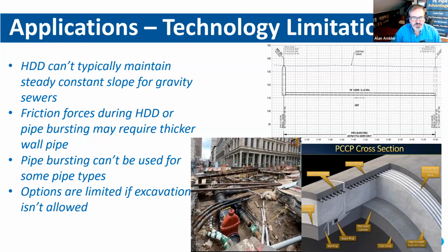So we just had a question from Randy about what types are suitable for pipe bursting. There's primarily a fracturable and a non-fracturable pipe. A fracturable pipe would be something that breaks fairly simply: a cast iron, vitrified clay pipe, asbestos cement pipe, a non-reinforced concrete pipe. You can cut through PVC pipe with a splitter, high density polyethylene pipe, or other pipes like that.